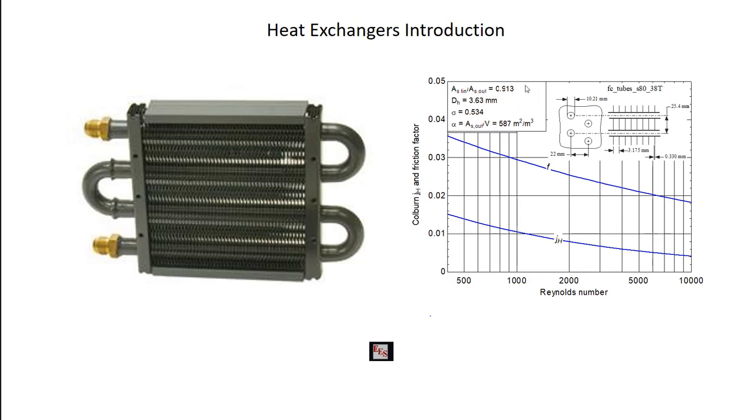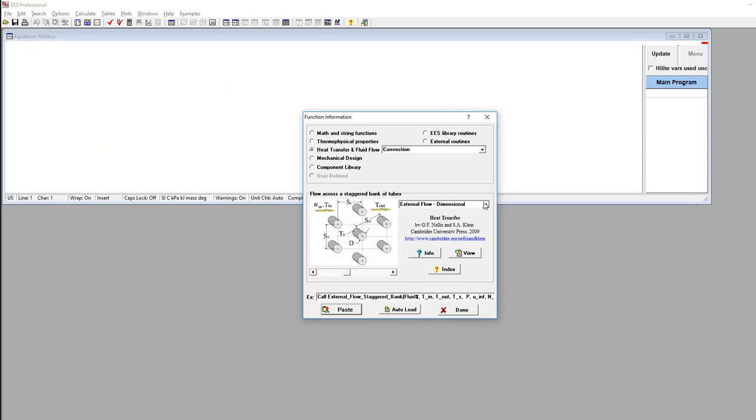So these are all geometric parameters. And then this F and J, these are the non-dimensional pressure drop and non-dimensional heat transfer, right? So F and J, and you have to understand how those things are defined. One thing that's actually really cool in these, you won't appreciate until you try to do a heat exchanger calculation with one of these, is these libraries have been put into EES.